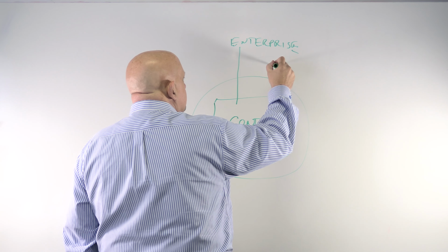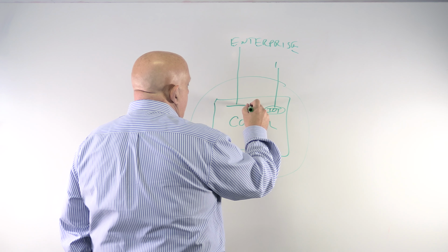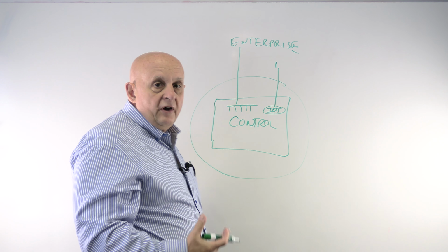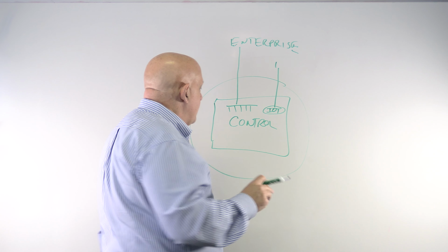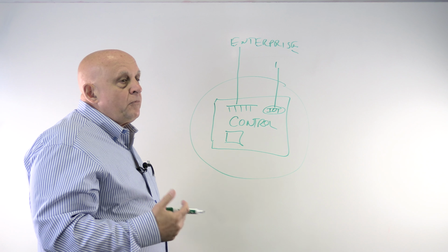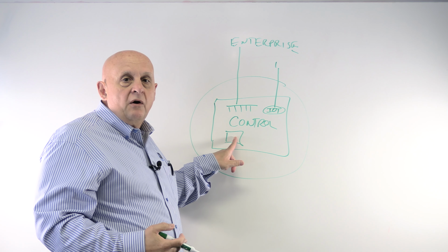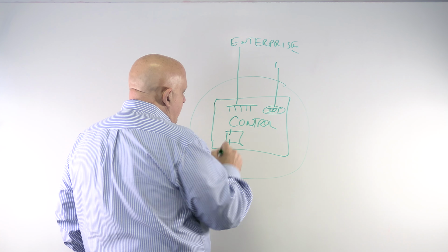There are a couple of things we can do here. Gary Workman and I are writing a book together on how to design Ethernet IP control systems, and we talk about this very thing in there. The idea is to separate all of your control devices on one network, so that those things all communicate on that network. Siemens was the first to come out with a motor drive that had 2 connections, one for control and one for IoT.